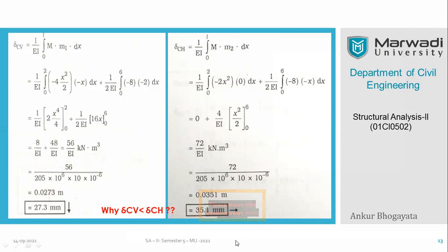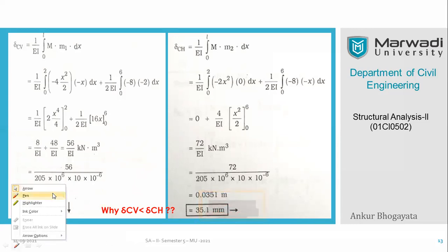I'm sure that you may have heard the term slenderness also. Slenderness is a property of a material or component where the ratio of length to lateral dimension is taken, and the more the slenderness, the more flexible the member, and more unstable also. Since you have not raised your hands, let me slowly give you the answer. Let me explain it very graphically and very quickly.